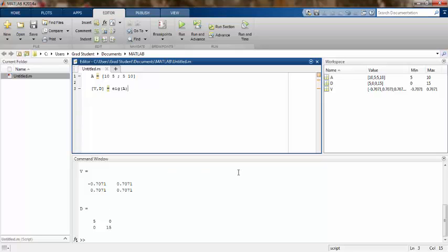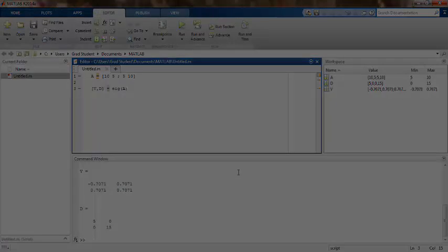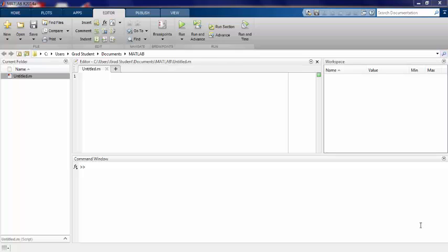Alright, if you've already looked through the example problem provided for you on iLearn, you will notice the tremendous amount of time this MATLAB command saves us compared to trying to work it out by hand. Take notice that the example we just did involves only one matrix for your input. In the activities you will work in this week's lab, you will have two inputs, your stiffness and mass matrix. A full breakdown and explanation of how this works is available in the lab background. Now the eig command in MATLAB with two inputs is virtually the same and is also shown in the background.